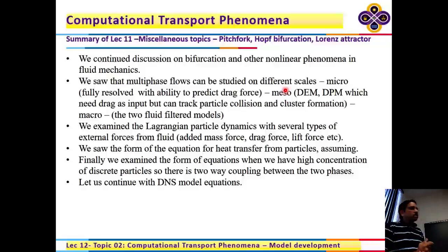And we saw the models that are used for Lagrangian particle dynamics, where you have many thousands of particles in a fluid domain, and how they evolve. They are determined by Newton's law of motion, very similar to what you do in molecular dynamics, where molecules are treated as discrete particles interacting with each other through force fields. In the hydrodynamic situation, these are particles interacting with each other through a force field, but that force field is purely hydrodynamic. So the intervening medium is the fluid, and by solving the fluid mechanical equations coupled with the particle dynamics, you can resolve that fully.